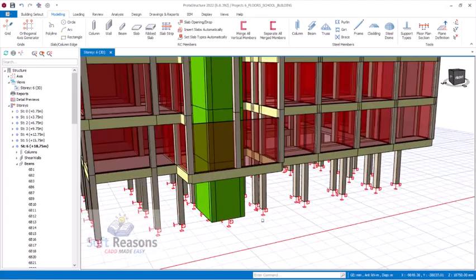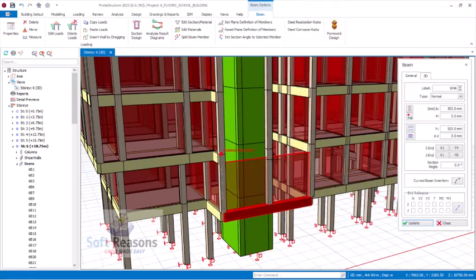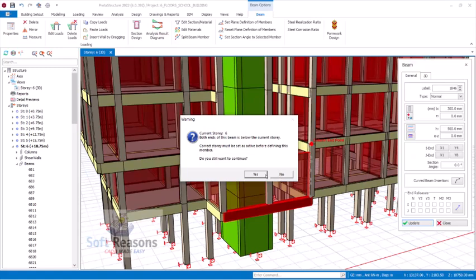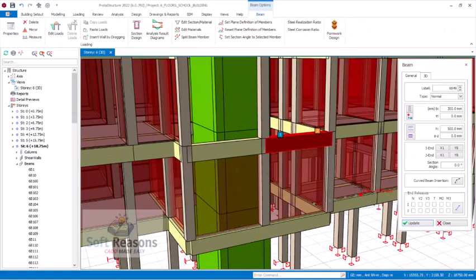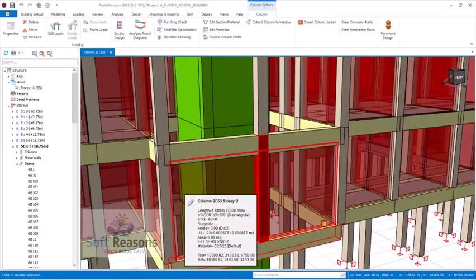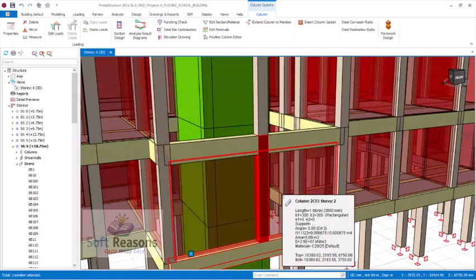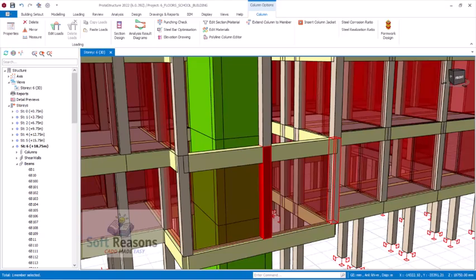Now I want to be creating a beam, so you just use the property right there, pick this column here, put this one here. We say yes to split it, so the load can be transferred evenly to this column and can be shared with these columns. The load on this beam can be shared between these 3 columns, so that you can lift these 2 columns.